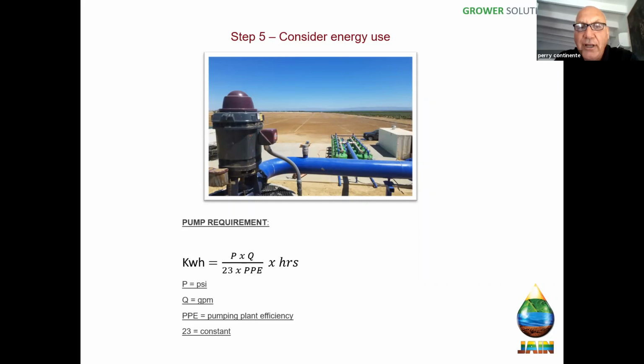Essentially, what we're targeting is a system with a variation in flow rate that will give us a distribution uniformity of 0.9 or higher. That's sort of the minimum required that's reasonably cost effective to provide to the grower. And generally, most crops are going to do well under those situations.